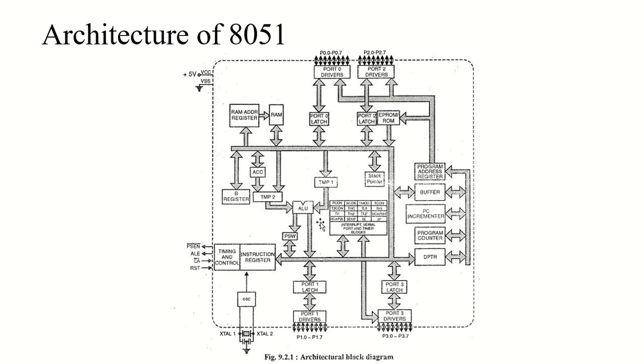Then we have the bit addressable area of 16 bytes, and in this area 16 bytes of internal RAM has always been reserved, whose address ranges from 20H to 2FH, and this 16 byte provides us with 128 bits forming addressable bits, and the microcontroller has given addresses to these bits ranging from 00 to 7FH, right?